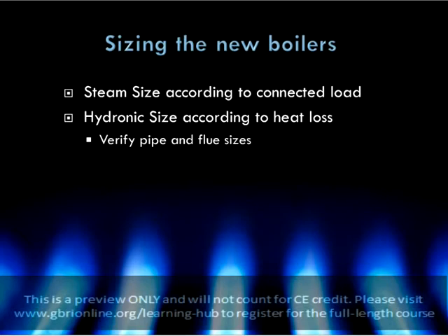Now, hydronic systems or hot water systems are sized according to the heat loss, the complete opposite of the steam system. And on those, you also want to verify your pipe sizes and your flue sizes, to make sure that the pipe going out to the building is large enough to handle your new load and new boilers.